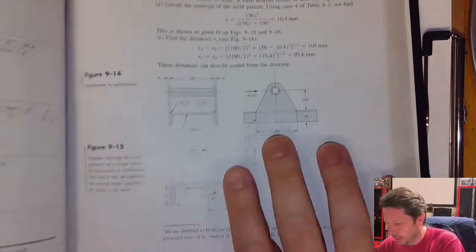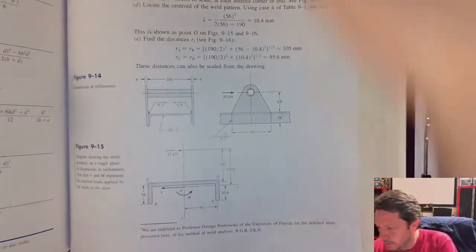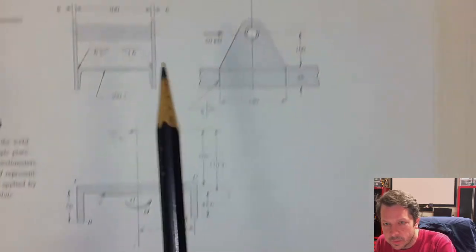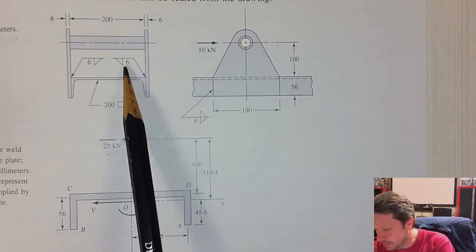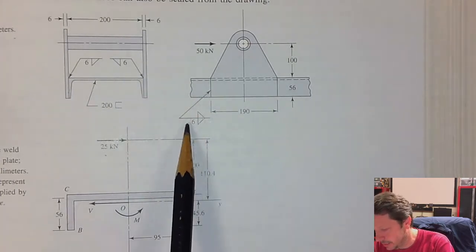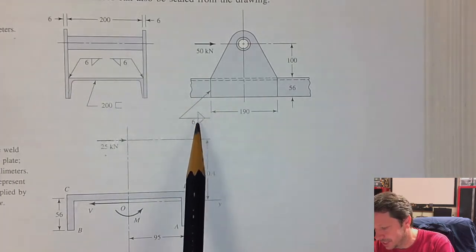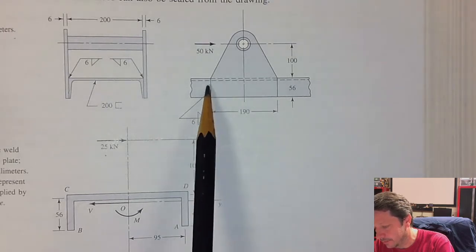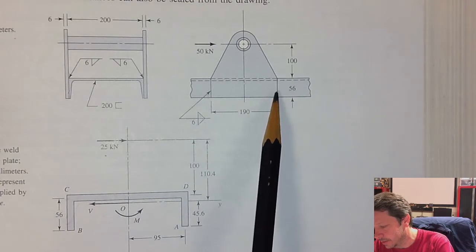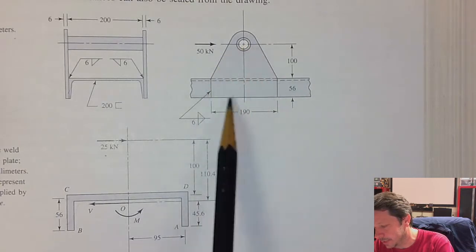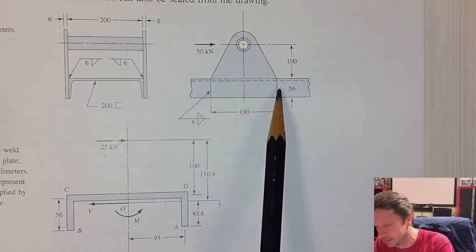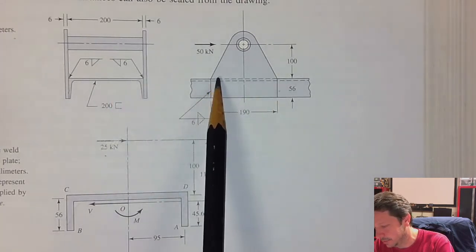So it tells us a couple of things here. One is that it tells us the weld sizes. We've got 6mm fillet welds in here. This one down here is telling us we have 6mm fillets on both sides of the arrow. So that refers to this side, and then the other side of the arrow is way over here. So we're talking about the other side of the plate in that case. So 6mm fillet weld here, 6mm fillet weld here, and then this one is indicating the 6mm fillet weld across